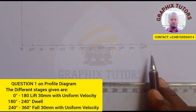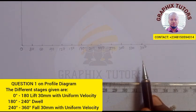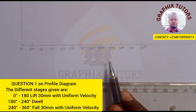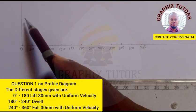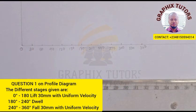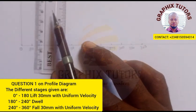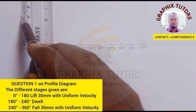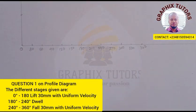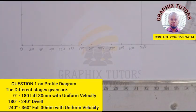What we're about to do, we'll call the profile diagram, right? This is a profile diagram we're about to do. Now after that, the next thing I'll do is, what will now be the height? The height is always the lift or the rise. That will be the height of this profile diagram here, and we're given it to be 30. So I'm going to measure 30 from 0 to 30. Can you see that? And I'm going to take here up this way, and I'm going to close here too this way.